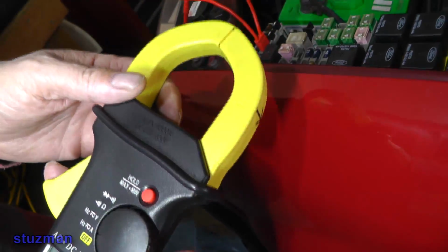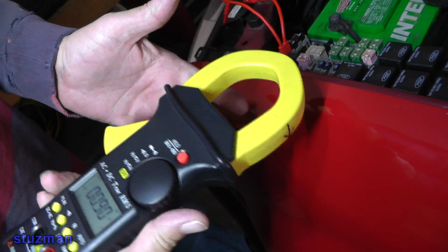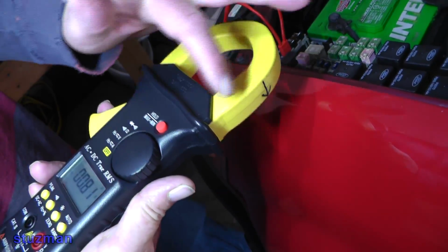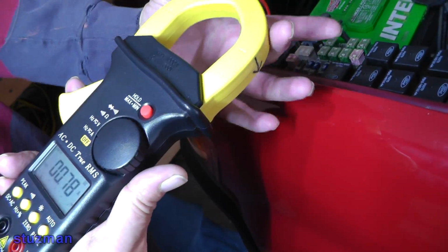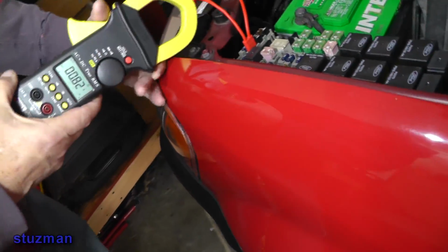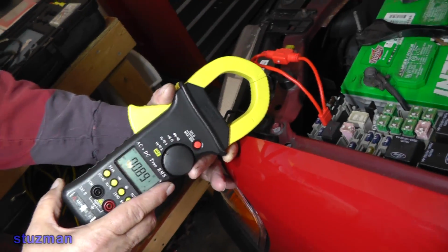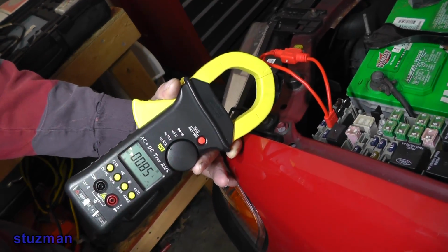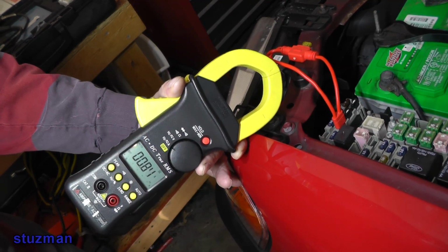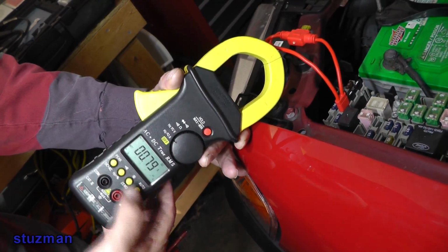One of the first things I do is open and close the jaws a few times. What that does is demagnetize the jaws, if you have any kind of residual magnetism in the jaws there. Now, most amp clamp manufacturers recommend, not a requirement, that you get next to the wire in a similar orientation to how you're going to be putting the clamp on, and you want to zero it.